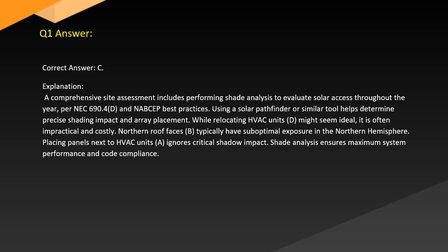Answer. Correct answer: C. Explanation. A comprehensive site assessment includes performing shade analysis to evaluate solar access throughout the year, per Annex 690.4(d) and NABCEP best practices. Using a solar pathfinder or similar tool helps determine precise shading impact and array placement.